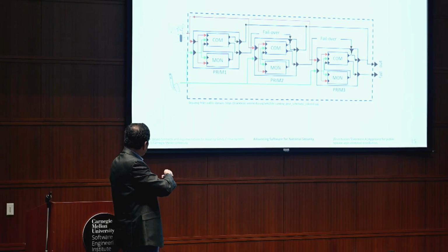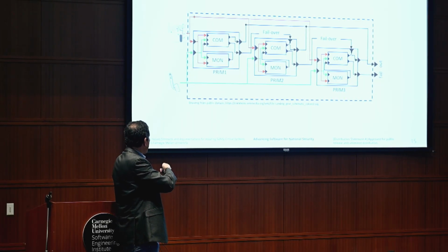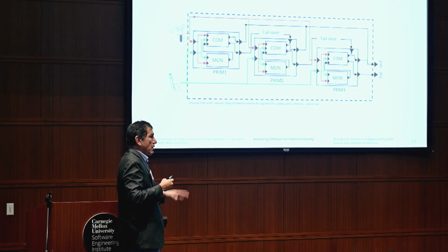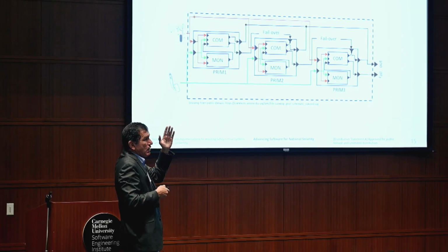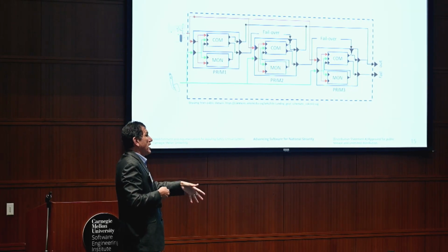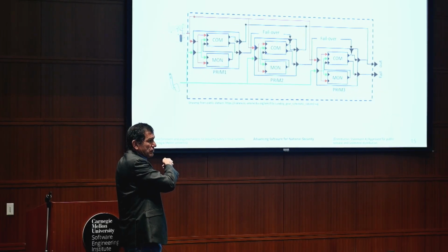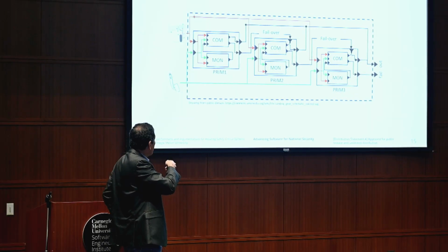These are control systems, so they control two things. They use the pedal of the pilot to control the rudder if they are in the air, or the wheels if they are on the ground. So they have a sensor, the weight on wheels sensor, to find out whether they are flying or on land.